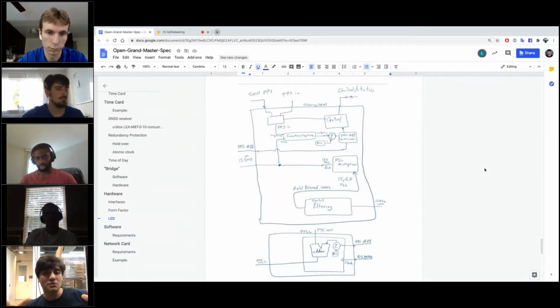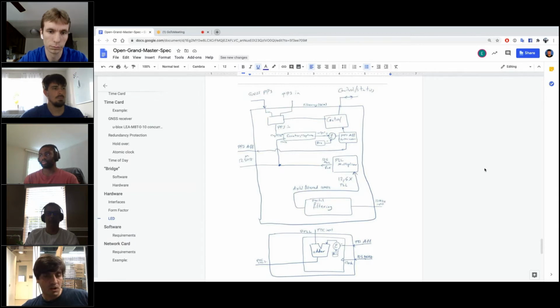The counter is running the beats of your atomic clock, and you take snapshots from the GNSS that you get in, and then you see how far they are from a second. You use this to tweak your VCO or PLL. This is called disciplining your oscillator.